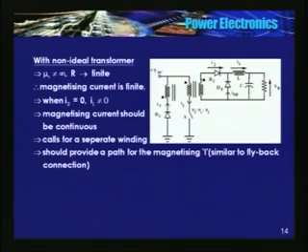What happens if I consider a non-ideal transformer? Let me tell you one thing, you cannot have an ideal transformer. Mu r is finite, not equal to infinity. Reluctance R is finite. If R is finite, the ampere turns required to establish the flux in the core is again finite, not 0. The source has to supply some ampere turns to establish the flux in the core.